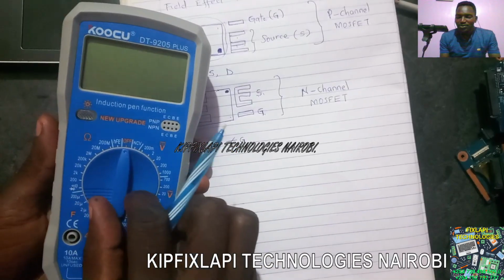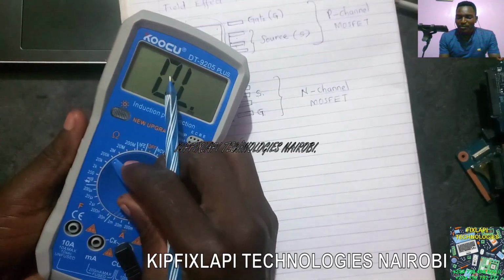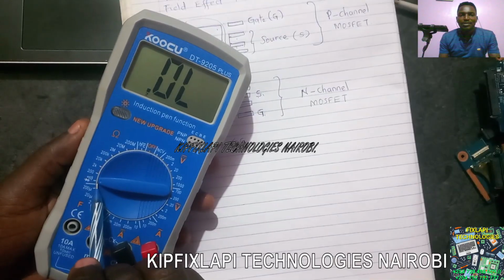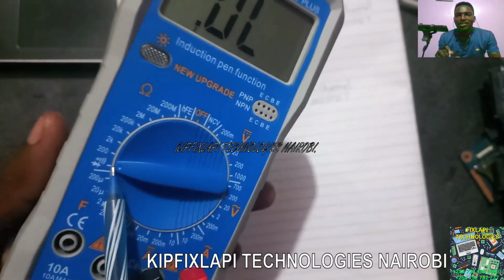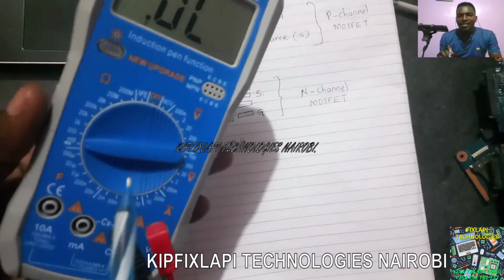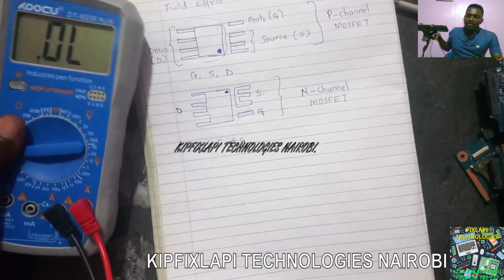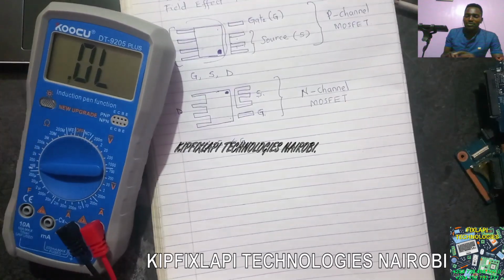So what you need to do is to turn on your meter and make sure your pointer points at the continuity mode. This is called continuity mode. So I believe you can see it. So this is the continuity mode. This is the point where we can test the continuation of a particular path, or at that calibration, it will show us which point is connected to what point, right?